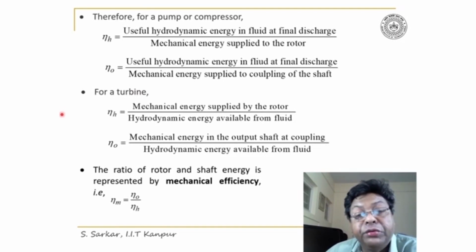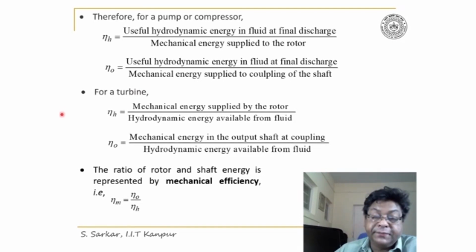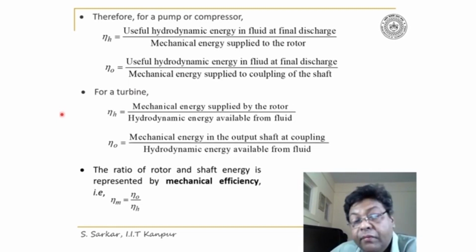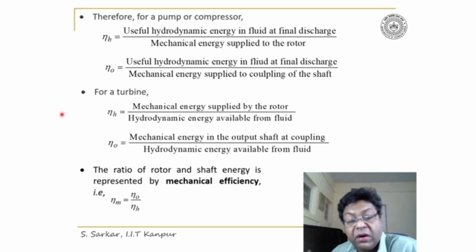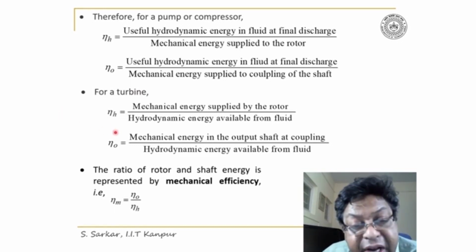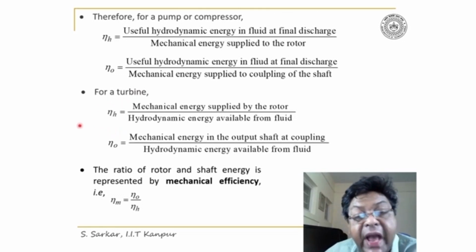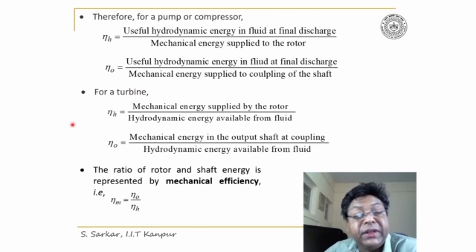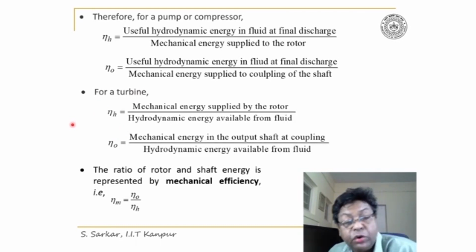So this equation can be stated as: the rate of change of phi in the system is equal to the rate of change of specific property within the control volume plus the net rate of efflux of phi across the surface.